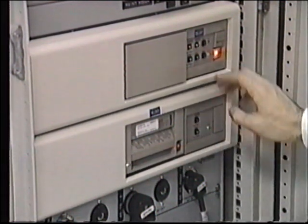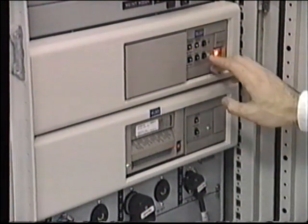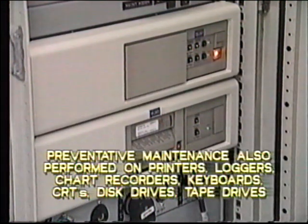Regular preventive maintenance is also performed on items of equipment which are subject to wear and tear, such as printers, loggers, chart recorders, keyboards, CRTs, disk drives, and tape drives. Maintenance of the software programs involves debugging and revising the program or updating to meet changes in the power system. This work is normally carried out by the equipment supplier or perhaps a special department within the utility company itself.